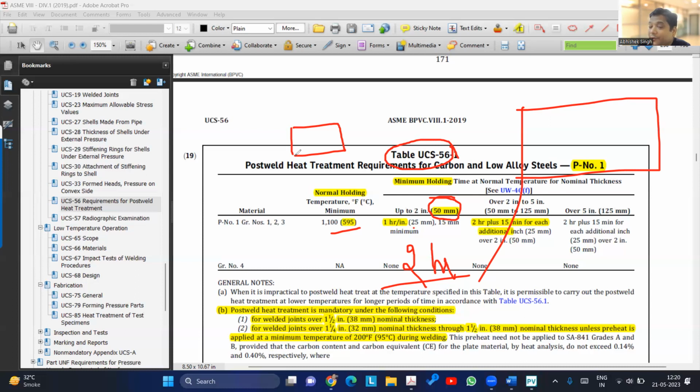Pre, why we do before doing post-weld treatment, we make sure that there is no repair, because if the repair is already there, which I can catch right now, then I'm adding that PWHT itself will become invalid. So there is no point. So check that if there is no problem before, then there are very rare chances that you will find a problem after doing PWHT, but it may happen.